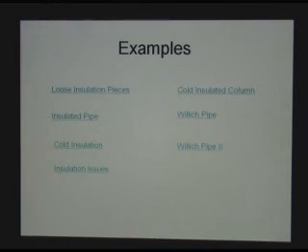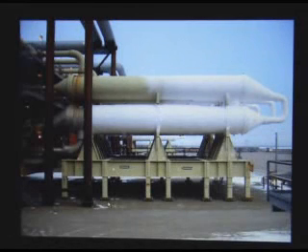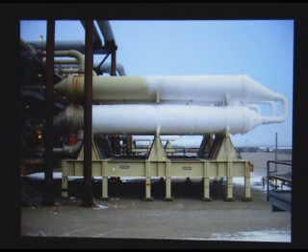Click on cold insulation. Here's a little example from the North Slope. The lower heat exchanger on the left-hand side is insulated with cold insulation. The rest is not. The reason was that the heat gain here is immaterial to the process on this side.